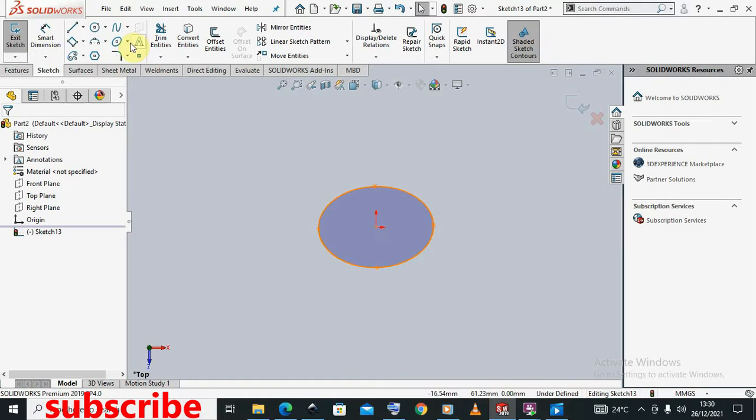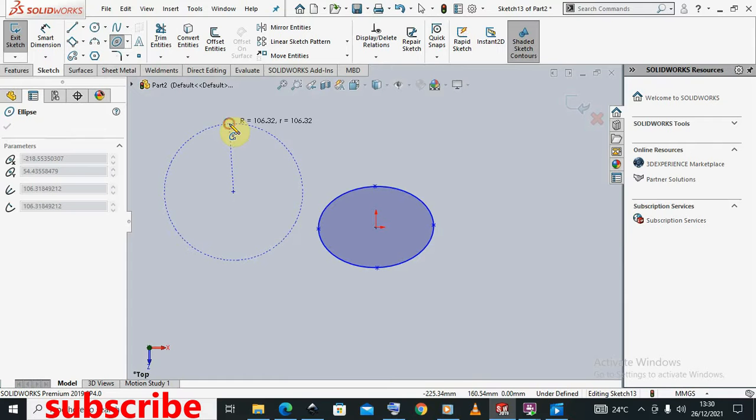So the other one is the partial ellipse. It's not coming out full unless you want it to be full. You'll come here, click the first point, get another point, then you come out like so. By dragging it all around, you can select where your ellipse will stop. You can make it parabolic, you can make it half like that, you can make it complete, or it could be like that.